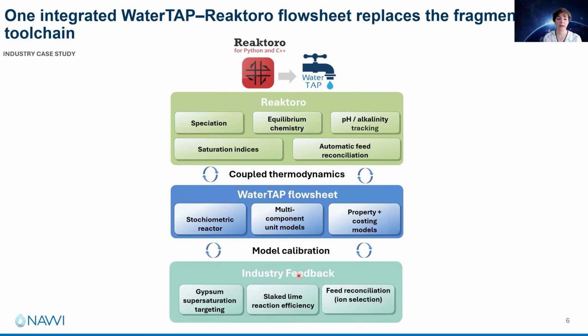And we also calibrate these two coupled models with the very valuable feedback that we received from an industry partner, Abraham Tech Resources. One of the most important pieces of feedback was regarding the gypsum supersaturation targeting: no matter how long the water sits in the softening reactor, you still have supersaturation of gypsum, and we include that in our modeling.